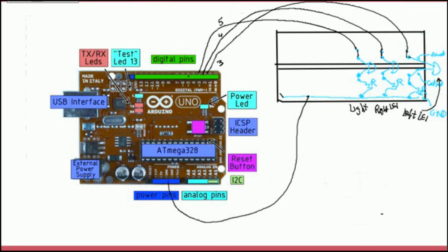Because not all embedded systems have internal pull-up resistors like the Arduino, although it simplifies interconnection, I'll use the traditional method with an external pull-up resistor.